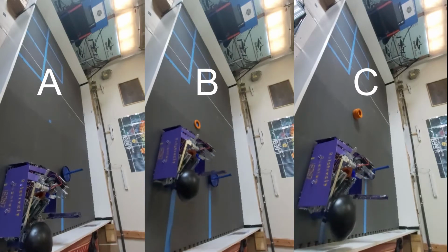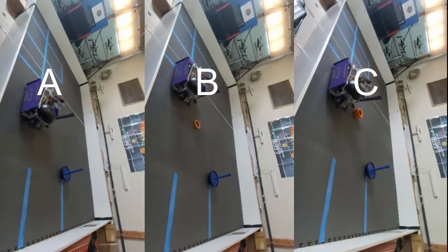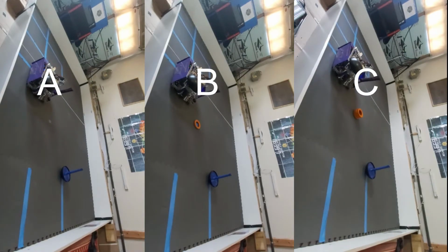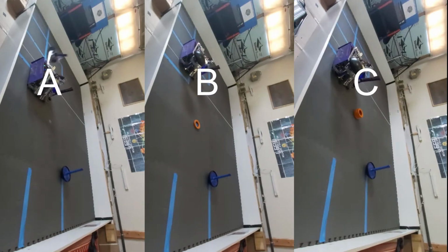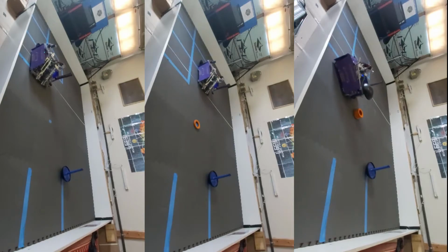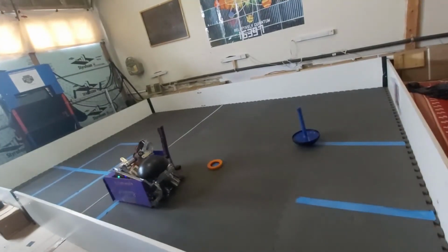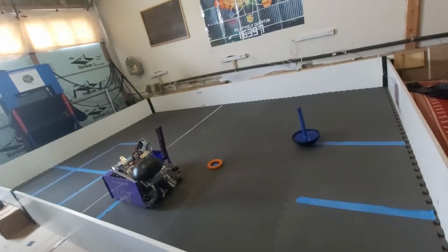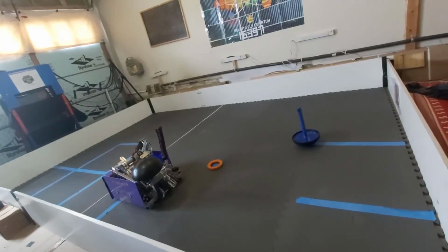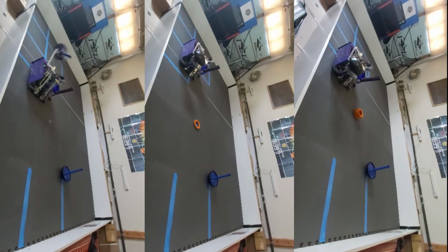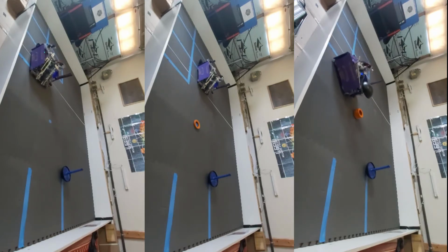We can now implement these techniques into our autonomous routine. We have 3 unique autonomous routines for boxes A, B, and C, depending on how many rings were detected to be stacked. So, we can quickly speed through each one and talk about it. All autonomous modes start in the same fashion. They all drive up a certain distance, slightly changing depending on the reading from the distance sensor, and then shoot the 3 preloaded rings into the high goal. From here, all 3 routines diverge slightly.